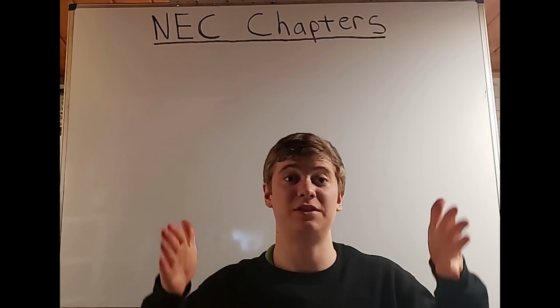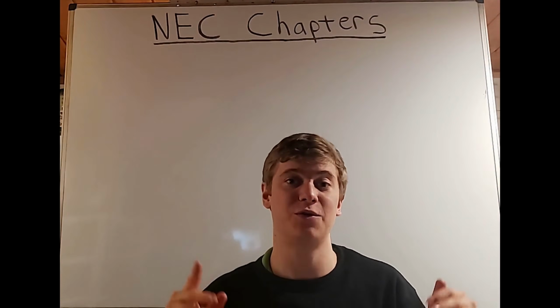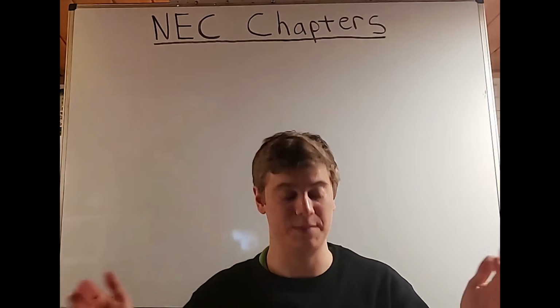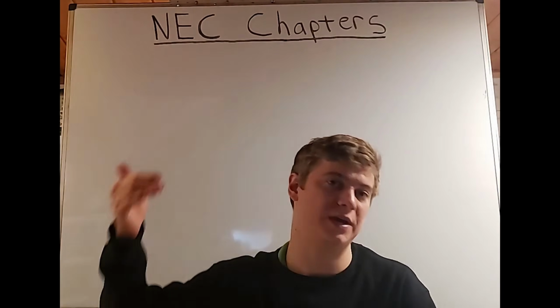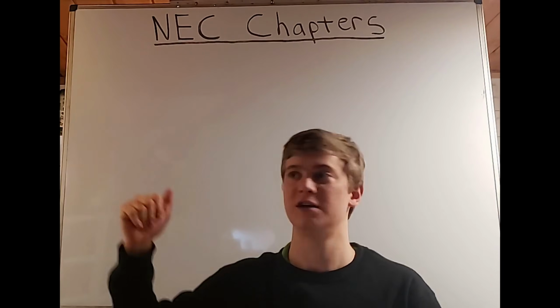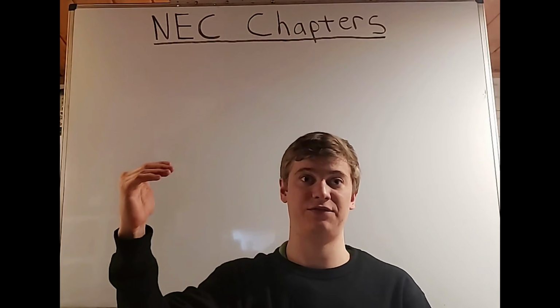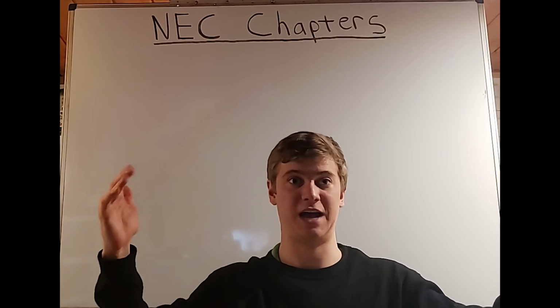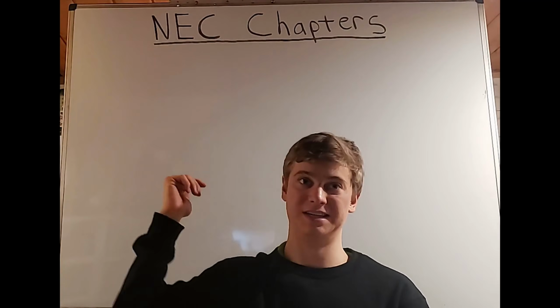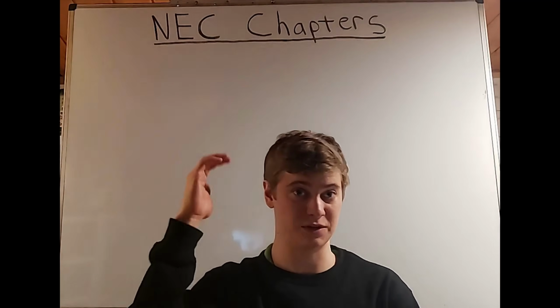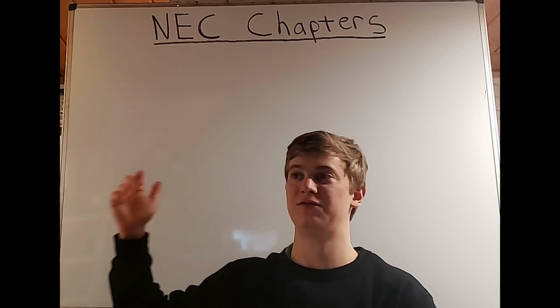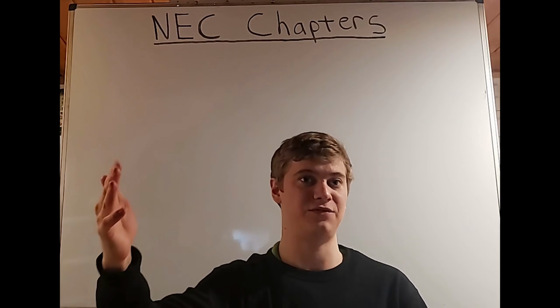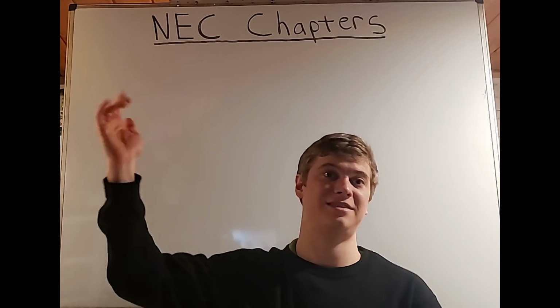That means if you have the width over 30 inches, then you're going to have the width of the equipment. Okay, we have the height of the equipment. We have a 6.5 foot minimum. So if the equipment is 6.5 feet, then we're going to have a 6.5 foot minimum. If the equipment is less than 6.5 feet, we're still going to have a 6.5 foot minimum. But if the equipment is over 6.5 feet, then we're going to take the height of that equipment.